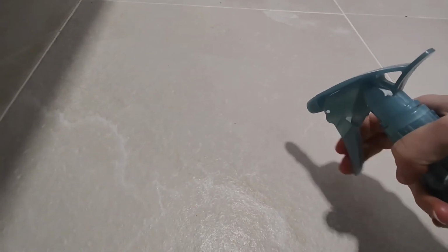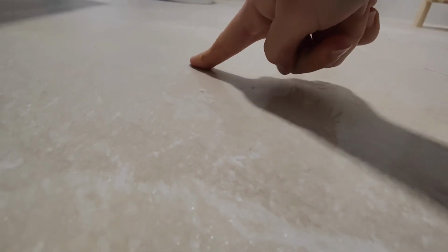But if we don't want to complicate things so much, we can just check in the store itself if it's going to be slippery. It would be similar to what we discussed earlier, but we would bring a small water bottle instead of a mixture. We wet the tile a little and then run our finger over it. And just with that little trick, we can already tell if, when that tile is wet, it's really going to be slippery or not. It wouldn't just work for the inside of the shower, but also for the outside. When my grandmother chose the tiles, she picked some that are really slippery, and we've had more than one mishap with those tiles. So I think checking whether they're going to be slippery or not is essential.